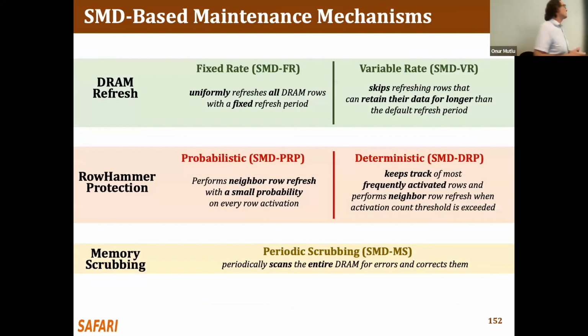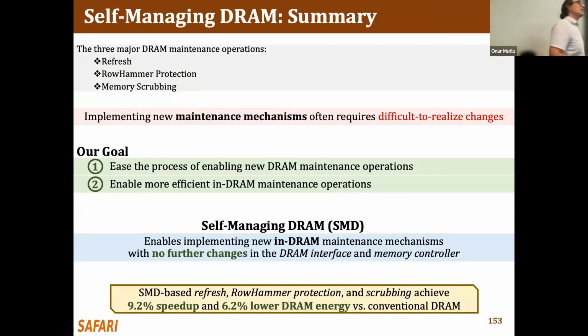And it's not just RowHammer protection. You can actually do DRAM refresh mitigation. A lot of the things that we have discussed, the DRAM manufacturer can figure that out, and it can do variable rate refresh, etc., without modifying the memory controller. I mean, they have a memory controller internally, of course, now, memory scrubbing, etc. I'm not going into the details of this, but I believe this sort of interface change is going to be important going into the future, except it's a tough area.